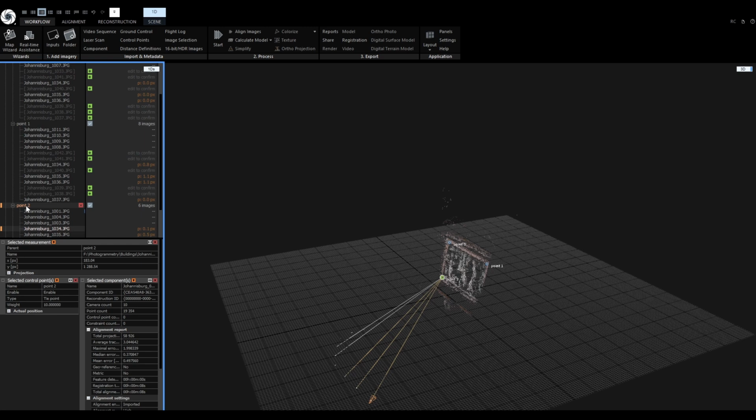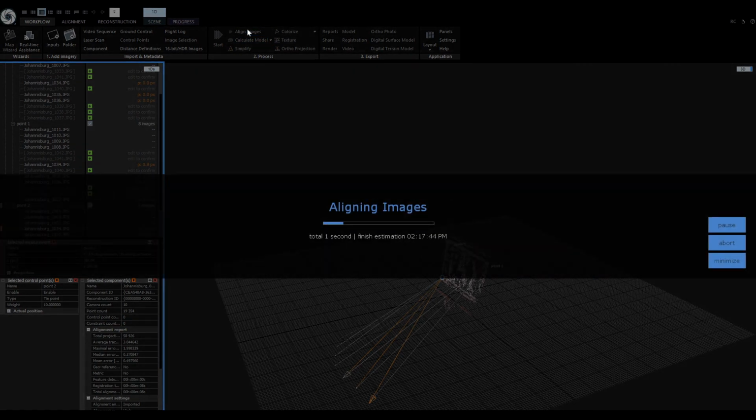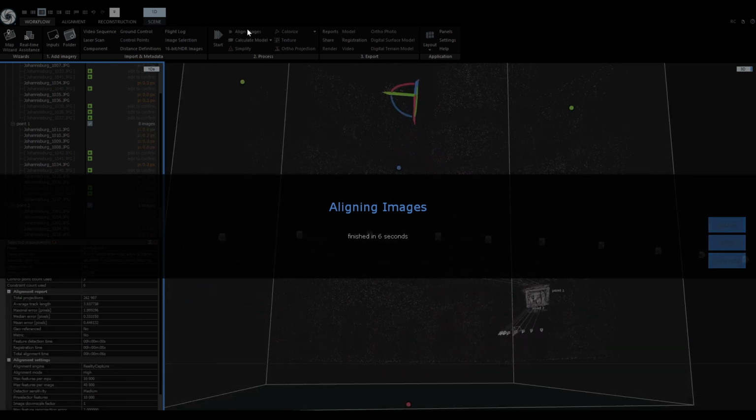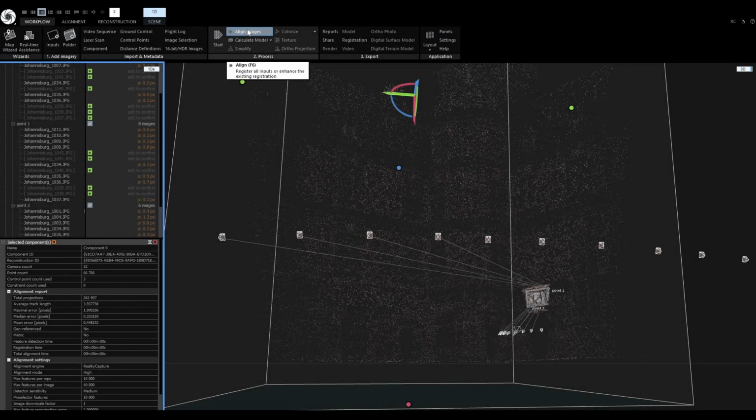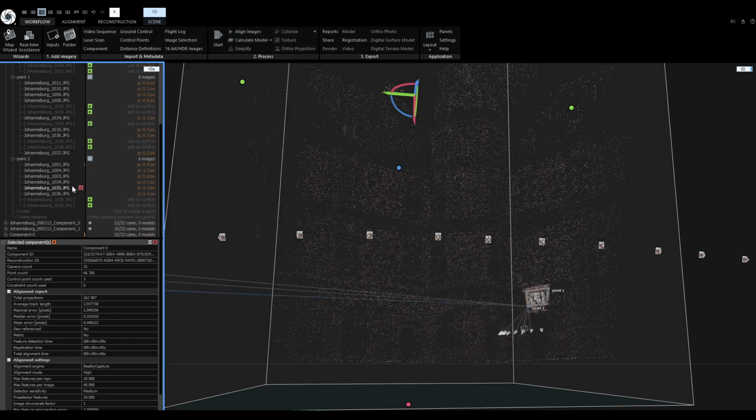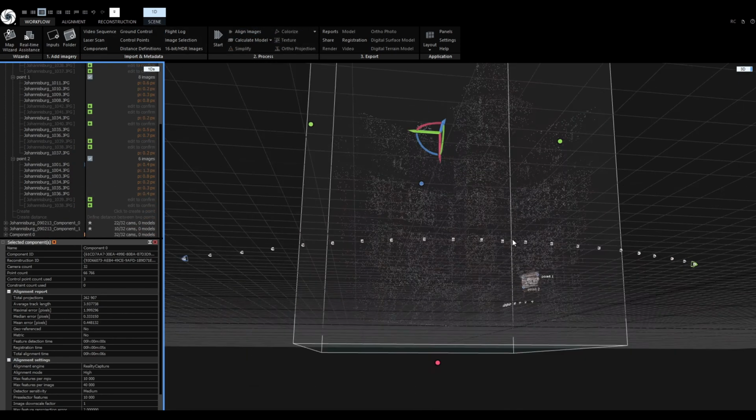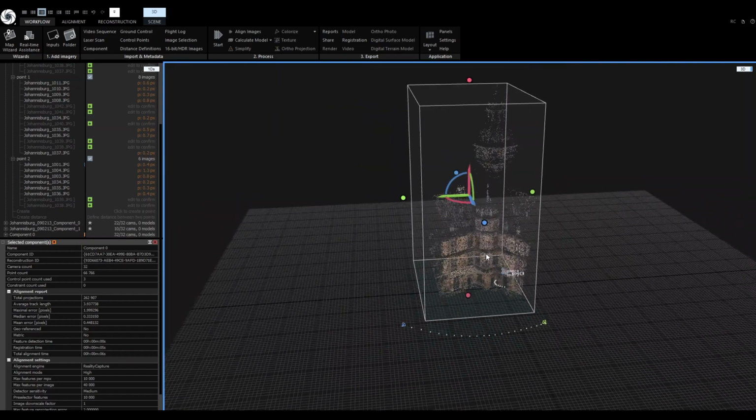And that is all I wanted to go over. Do not use control points as a primary modeling tool. Instead, add meaningful images when possible. Use control points as a last resort to merge components, to increase quality in alignments, and to fix misalignments. Hopefully after this tutorial, you will know exactly how to use control points in RealityCapture.